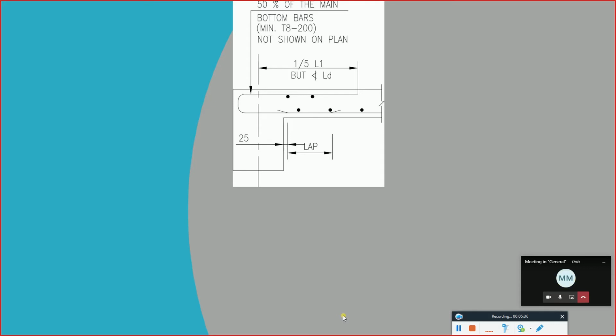Now, I'll show the pictures first. I'll explain what is this condition, and then we'll go through the different things inside this particular case. Okay. So this is representing a simple supported end, or a discontinuous end in the slab, where you can see that this is the last support. We don't have any other support in this particular area. So this is going to be representing an end support case for you.